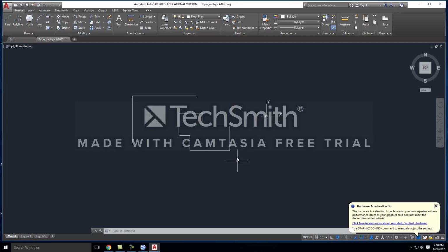Okay, so another little trick as you're drawing, and a trick that will help you become more efficient, is if you want to duplicate a command, so you just want to do that command again, all you have to do is hit the space bar after you use it. Let me backtrack. I do F for fillet. I select my first line and my second line. And if I hit the space bar, it will just reactivate that same command. So you don't have to put CHA again and then CHA again or F again. You can simply hit the space bar and keep using that same tool over and over.